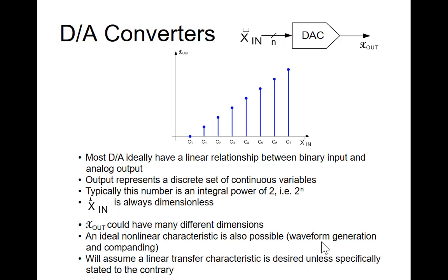Usually the number of bits of resolution is determined by using all possible codes for a given number of digits. So consequently, the number of outputs of a DAC is typically a power of 2, 2 to the n. I don't really know the reason for this. An 8-bit DAC will have 256 outputs. A 7-bit DAC has 128 outputs.